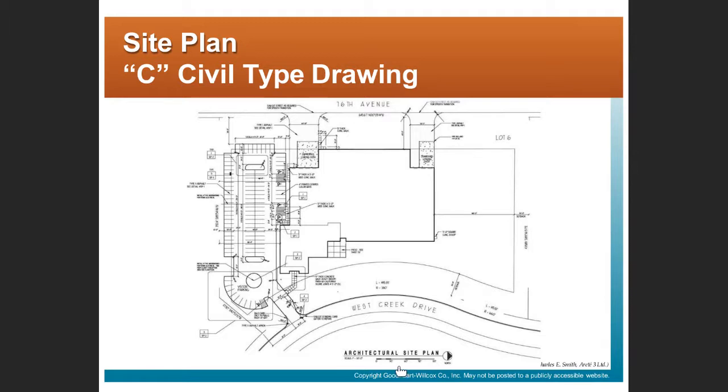You see a scale. Right, in this case, it's an engineering scale, so 1 inch equals 30 feet, right, differing from the architectural scale that we will typically see for the other sets of drawings. So again, there's a scale. We quite often see an indication of which way is north, so we can orient ourselves. We might have true north and project north.